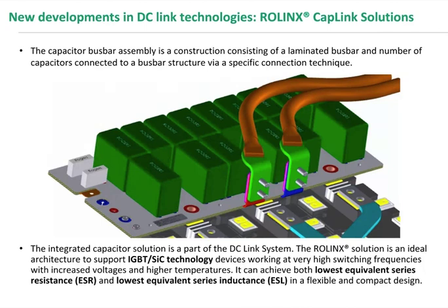We have also connected, in this example, IGBT modules, and those of you who had a chance to visit us at the PCIM show in Nuremberg last week saw that we presented this model. Overall, this is an answer to requirements in terms of silicon carbide technologies and low inductance. We developed this product, and we use some specific techniques to connect or integrate capacitors on the busbars. We have a patent ongoing.